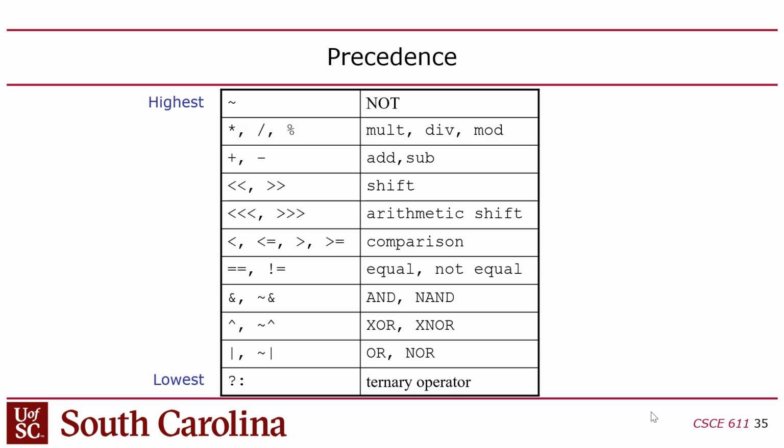You know, resources versus latency, basically time, the performance versus the cost. There are different multiplier designs. So you would probably never put a multiply, divide, or a modulo in synthesizable Verilog code. But like I said, you could put it in test code that you just intend to simulate. But add and subtract are usually pretty reasonable.